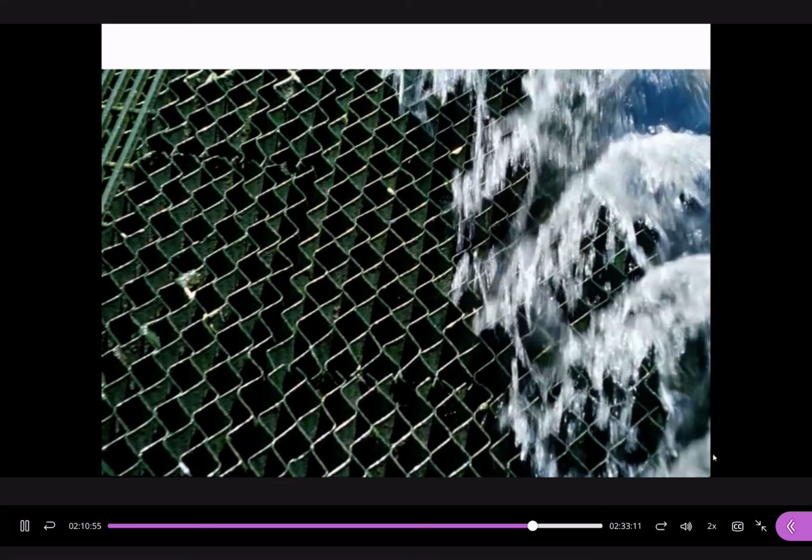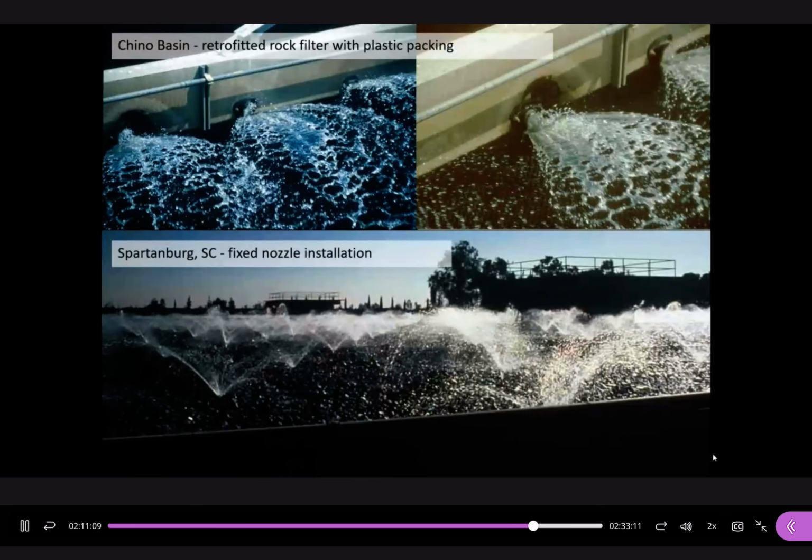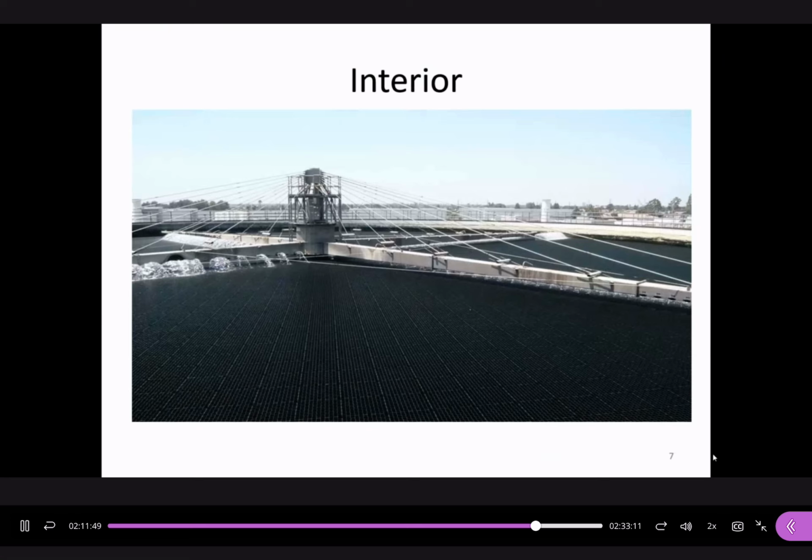So here we still utilize microbial function to degrade organics. We have different ways to distribute water to the media. You can see here we have some spray nozzles. Wastewater, and this trickling filter is made of rocks, and some media are rocks, some are plastics. Different materials. It could be a very large trickling filter, huge. This is the distribution arm. This is media.